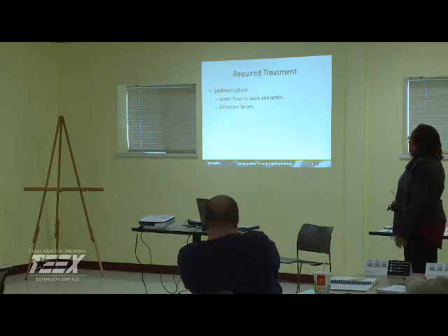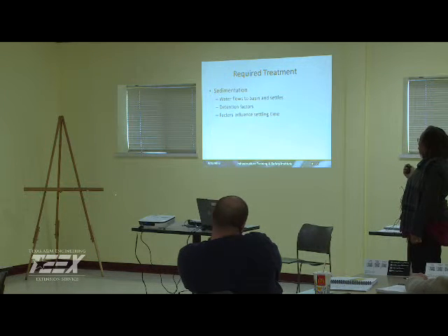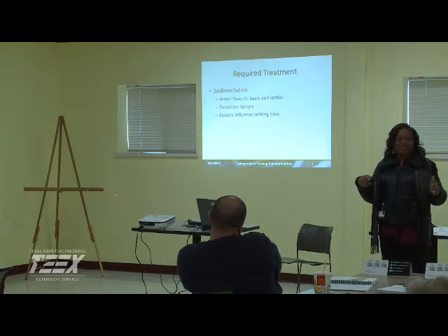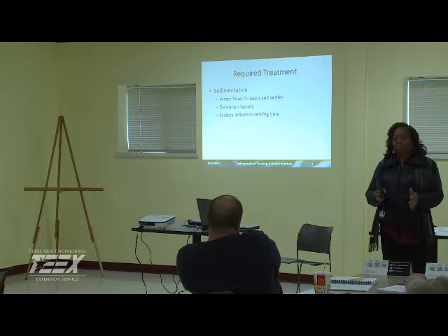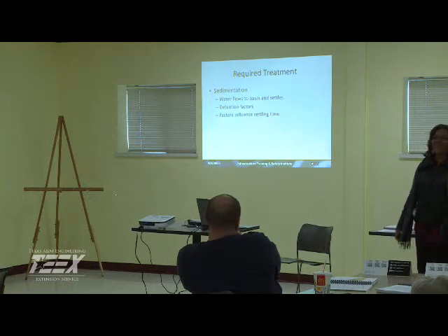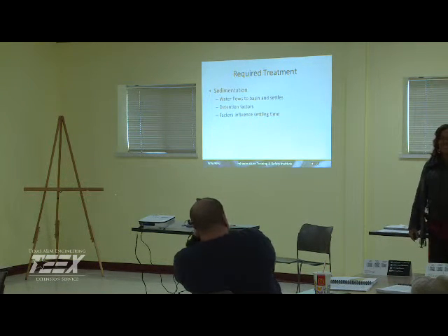That's the concept. All right, there are also factors that influence settling time. What are some of the factors that you think can influence settling? Temperature. Temperature, excellent. Type of flock, size of it. Size of the flock, the weight, very good. What else? Elevation, depending where you're at, the different elevations can affect gravity, can it? Okay, that's a new one on me.